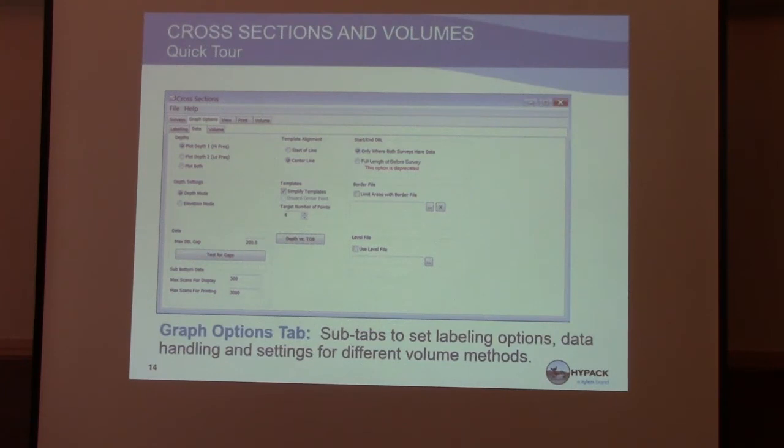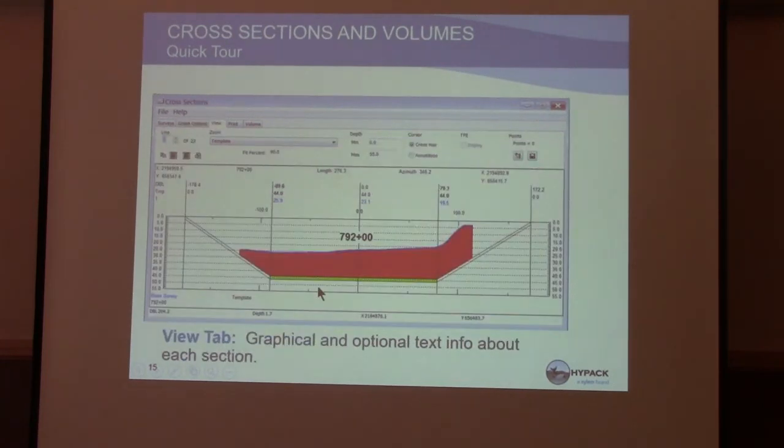I had to stop at the barge, and I picked up on the other side of the barge. It won't interpolate under the barge. We're not going to do that. We don't make up information unless you try to make up information. HYPACK won't do it for you. Template alignment, center line, that's just some ways you can align your template differently.